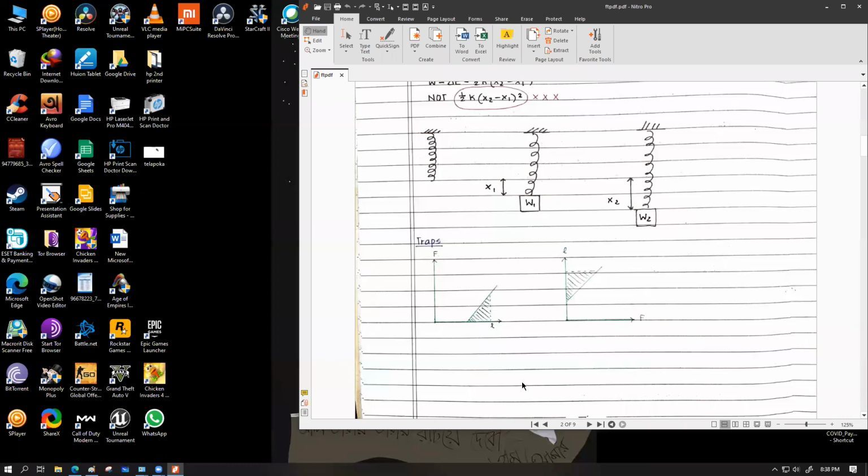Bujo, if you are trying to draw a graph of force versus length, you have to understand that when zero force was applied, the spring still had some length, right? When you did not apply any force, can the length of the spring be zero? না স্যার। No, it's going to have some default length. As you start applying more and more load, then the length is going to start increasing. That's why this graph is starting from a non-zero value on the x-axis. This part of the graph represents the unextended length of the spring, and then as you start to apply force on the scale, slowly your length is going to increase. So this is the extension part, this is the unextended length.